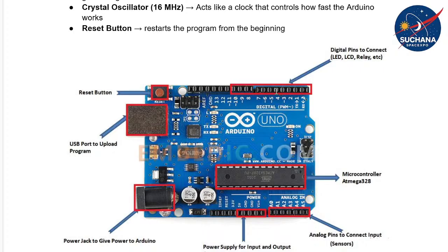Okay. See, every device, every component, to work requires two things, right? VCC and ground. VCC means a positive supply. Just for the sake of your understanding, you can understand VCC as a positive supply. Just like a battery has two terminals, positive and negative, hereafter we will be referring to them as VCC and ground. Okay. So ground means which is at lower potential, and VCC, as you know. Fine. So now one terminal you connected to the ground and the other terminal you connected to pin number 7. Now, should we configure pin number 7 as input, or should it be configured as output?